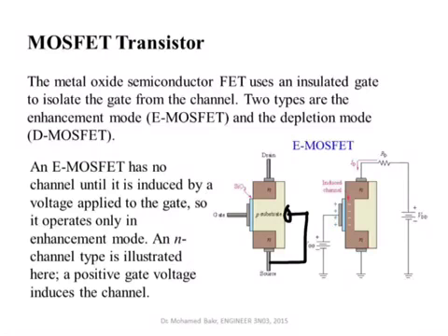And of course, this is called an N-type MOSFET because both the drain and the source are N-type materials, and current flows through an N-type layer, including this inversion layer of electrons that's created. We can have as well a P-type E-MOSFET. In a P-type MOSFET, this will be P-type, this P-type, and you have here N-type. And in that case, you have to apply negative voltage on the gate. Negative voltage on the gate will attract holes and then will allow current to flow between the two P-type materials.